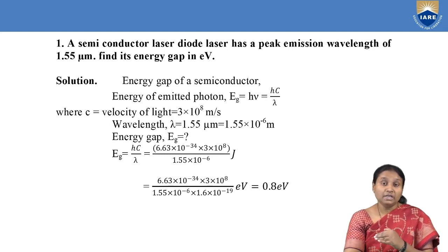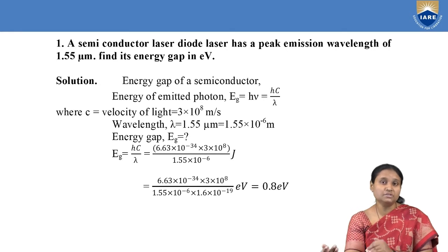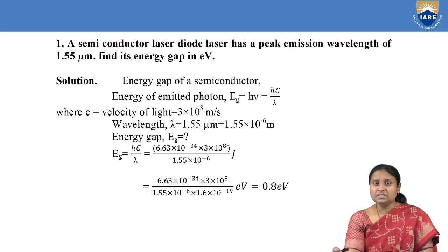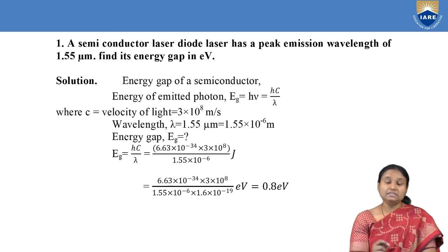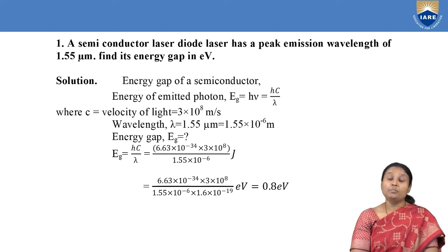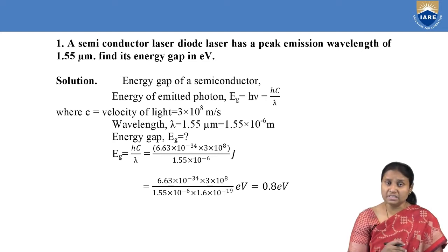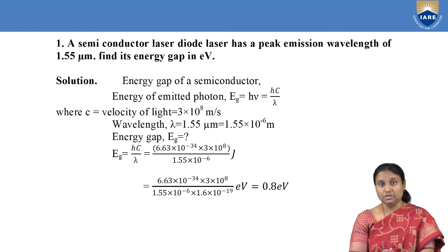Based upon what type of active medium we are using, we name lasers. In the case of semiconductor diode laser, the active medium chosen is a PN junction diode. And the PN junction diode is made with some special type of materials. What are those special materials? They are called direct bandgap semiconductors. These are compound semiconductors where we mix elements coming from different groups.